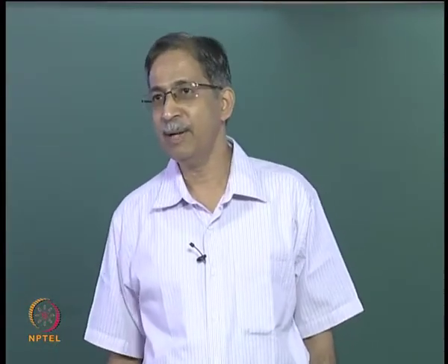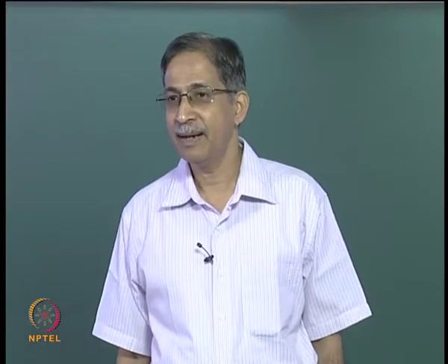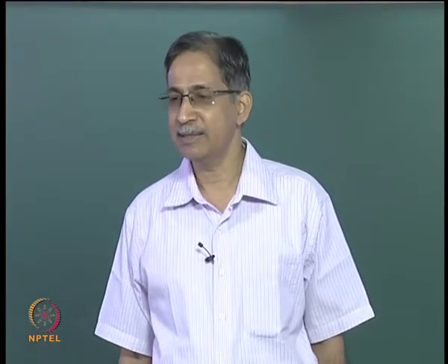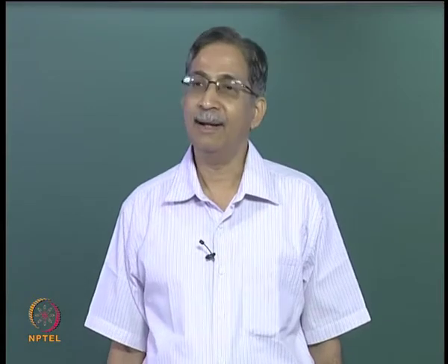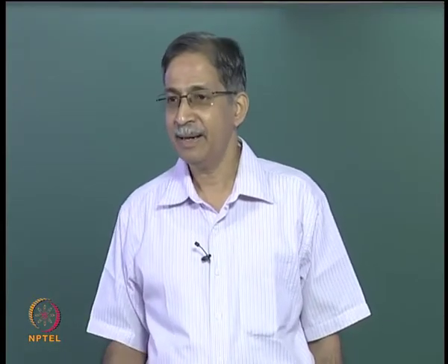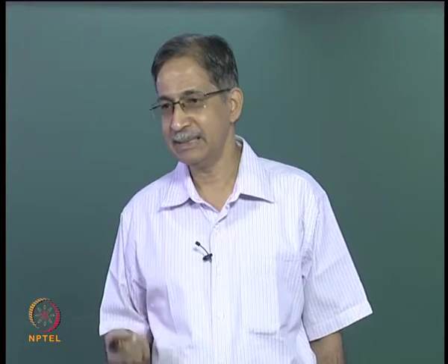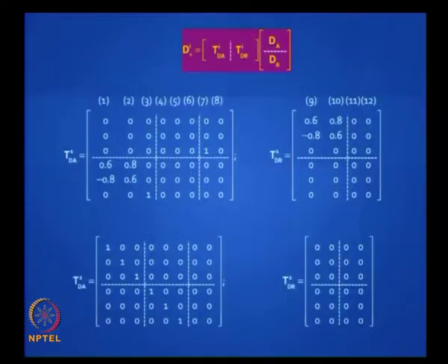So we are familiar with the TI matrix. You still have to rope in the cos theta, sin theta, sin theta and 1. So the method is the same, only thing you have to do it with your eyes open and fill up these matrices. It is convenient to separate out the active degrees of freedom from the restraint.